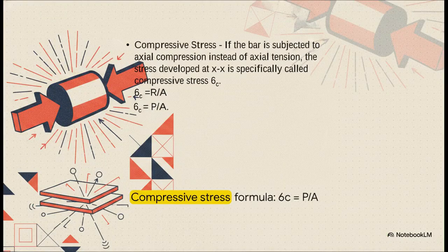Now, what if we reverse the force? Well, the formula mechanics stay exactly the same for compressive stress. Sigma C equals P over A. The math doesn't change, just the physical reality of it. The force is pushing inward, trying to crush the material, instead of pulling outward to stretch it.